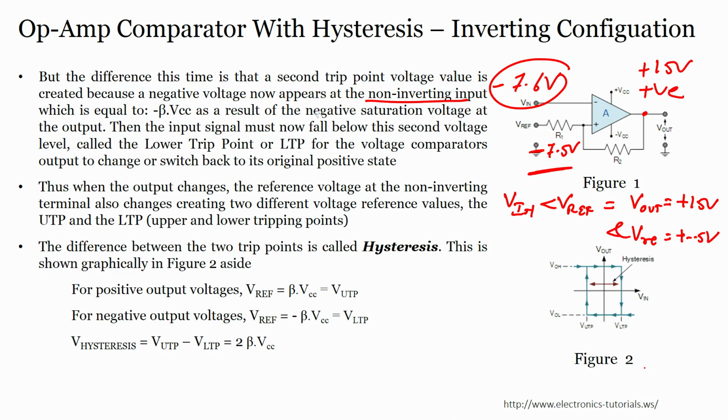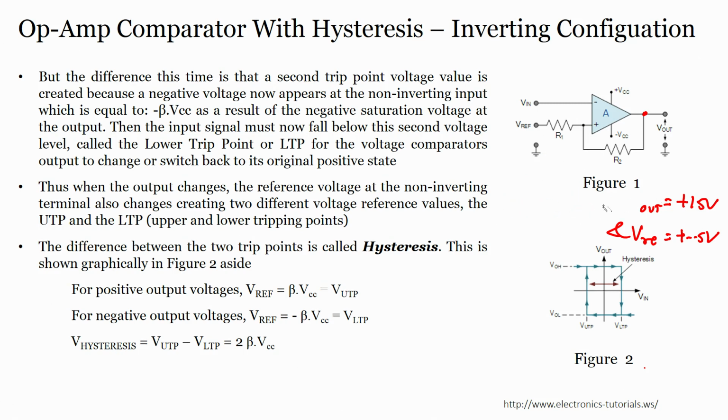Now, everything becomes super easy for you because you already know how to use the operational amplifier in various applications. When I talk about a comparator, immediately your brain works that yes, comparator is very easy: inverting higher than non-inverting, output is negative saturation; non-inverting higher than inverting, output is positive saturation. R1 and R2 are there, what else, the divider, R2 divided by R1 plus R2, or R1 divided by R1 plus R2, right. If R1 equals R2 it is half times Vout, so easy. What is hysteresis, now you know what the upper trip point and the lower trip point are, right.